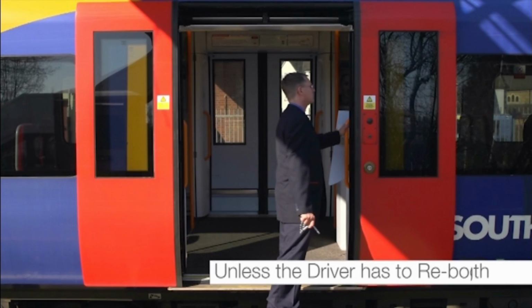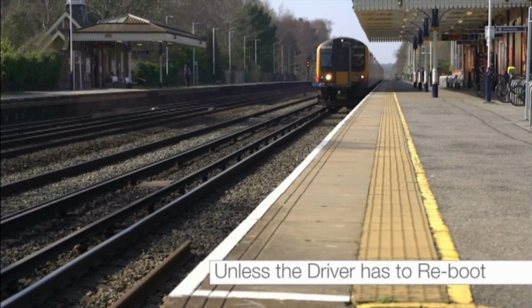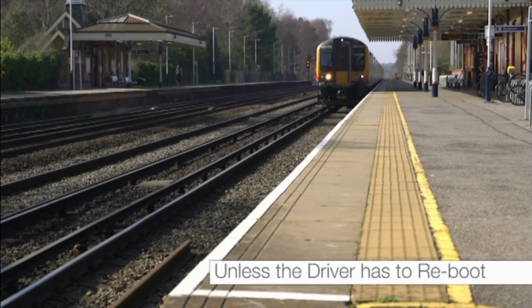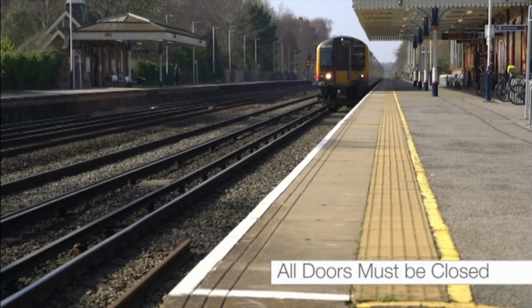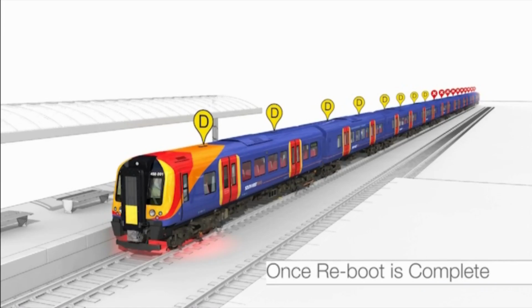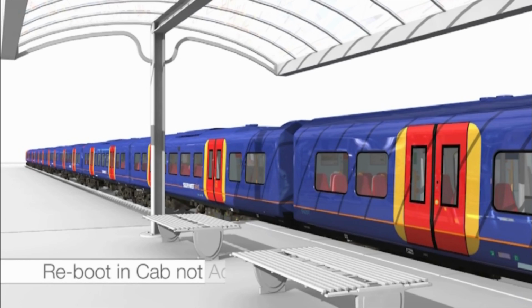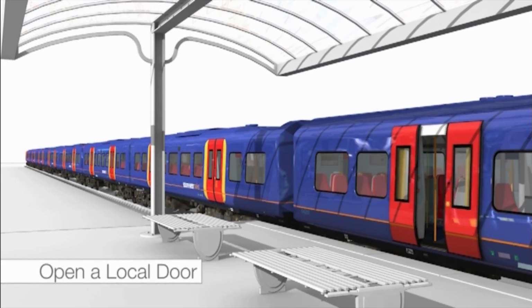The only occasion when the train will not remember the platform length without moving is if the driver has to reboot the train. All doors have to be closed in order to do this, and once the reboot is complete, the doors will open in default mode. If the driver has rebooted the cab of the unit not accommodated on the platform, then you must only use a local door to allow passengers to board the train.